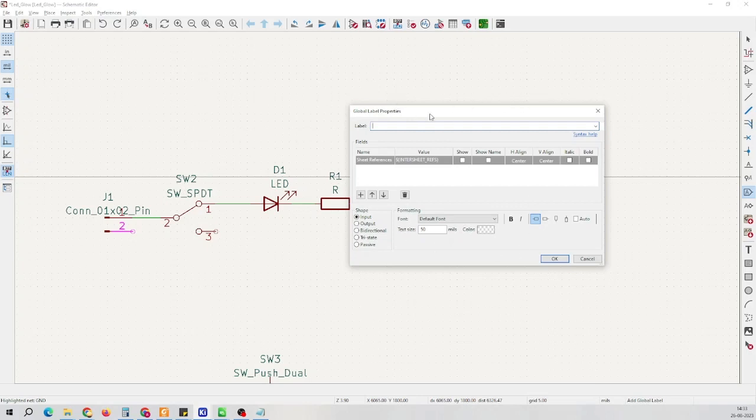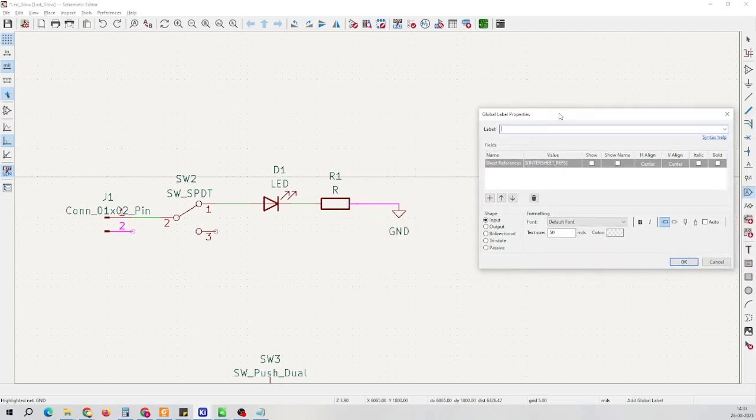So once this window appears, we don't want to physically add a net and connect from this point to this pin, but that can be removed by using a global label. And here we will be using the global label as GND. So you enter the name, it should be the same. Even the capital and the small letters should match. Only then will the labels be connected.